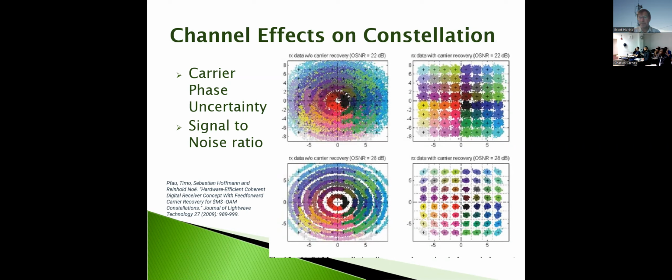So if our channel allows us to send 1,000,000 symbols per second, let's say, so its bandwidth is on the order of a megahertz or 2 of bandwidth, I'm totally hand waving that right there, then that's fixed depending upon how much spectrum, at the RF level, we're available to. So we can send 1,000,000 symbols per second.